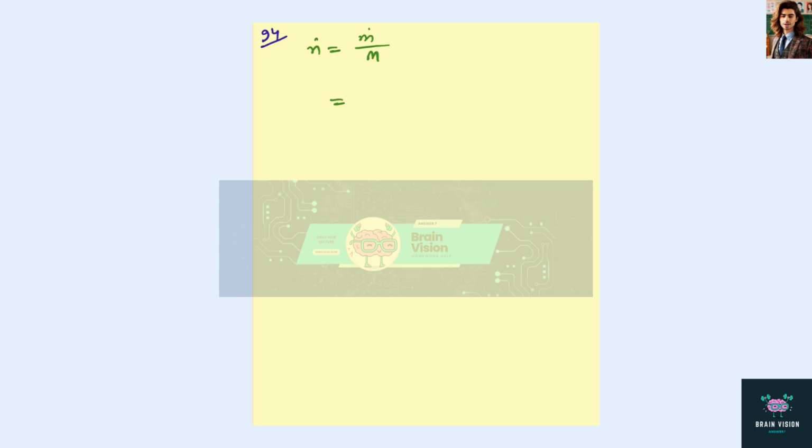The mass flow rate given here is 150 SCF per minute, and the molar mass is 359 SCF divided by pound mole. Therefore, the molar flow rate is 0.418 pound mole per minute.